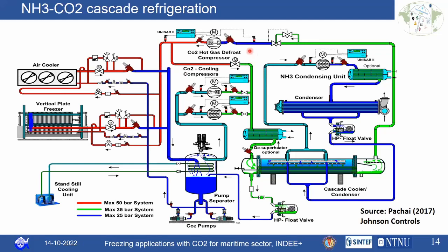So you can see the defrosting lines that have been installed in this evaporator. Here the defrosting will be done by a process called hot gas bypass defrosting. Hot gas bypass is nothing but the hot gas from the discharge of the compressor, the hot vapors from the compressor, being taken and, instead of being sent to the condenser side, sent to the evaporator, where you have the frost deposited so it can be melted away. So that also has to be taken care of. But during hot gas defrosting, you have to take care that the pressure will be more. So your design pressure should be more.